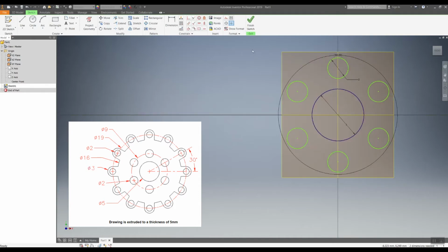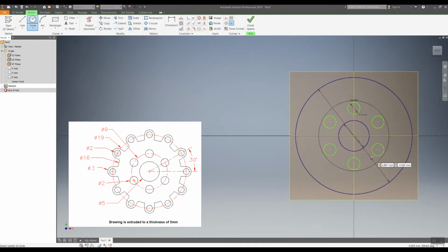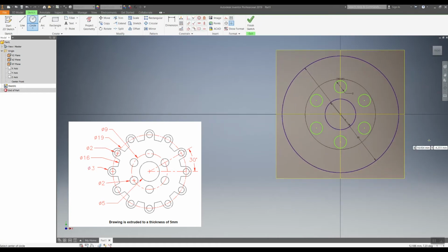Now we can work on this outside circle here. And if you look, it has a couple of dimensions. That midpoint that I used in the last one is 19. So that's a good starting point. Let's go there. Click there, 19. That would be my midpoint for my circle up here. What size circle is that?